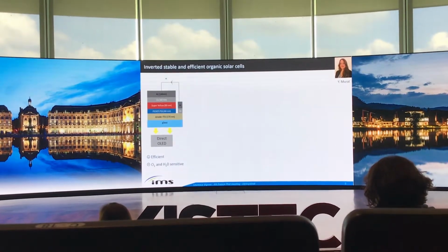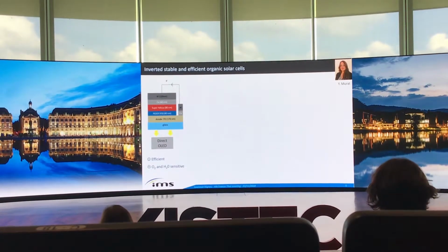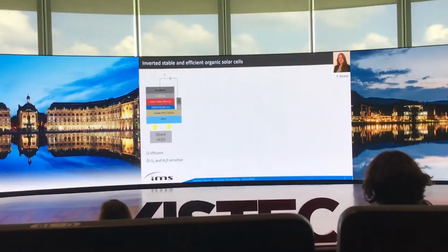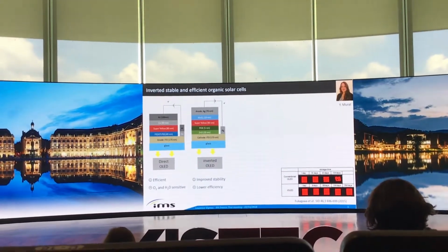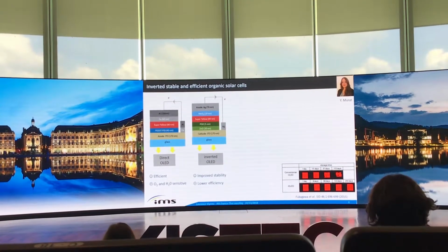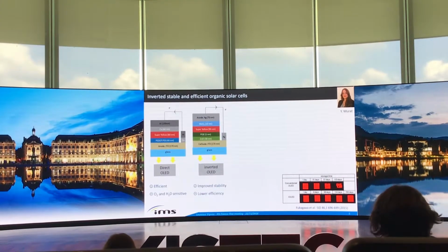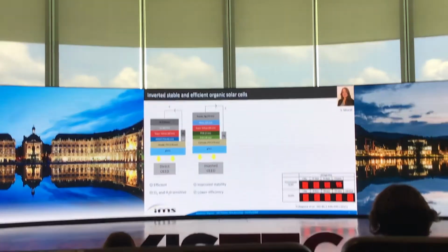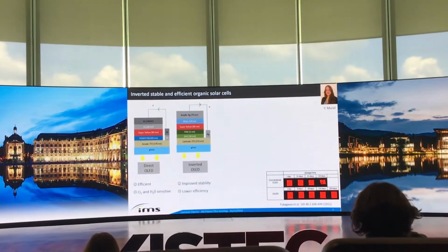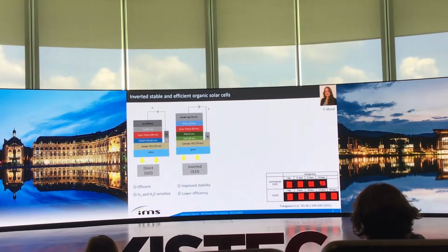These kinds of OLEDs are very efficient. This is the kind of OLEDs you have in your telephone displays, but they are water and oxygen sensitive. This is why they are encapsulated with glass. So what we try to do is to reverse and to make more stable OLEDs using an inverse structure, which means that the electrons have to be injected via the bottom electrode, the transparent one actually, and the holes via the top electrode. In the literature, it's pretty recent, but you can find some papers showing that this kind of structure is much more stable, as you can see here, than conventional OLEDs.